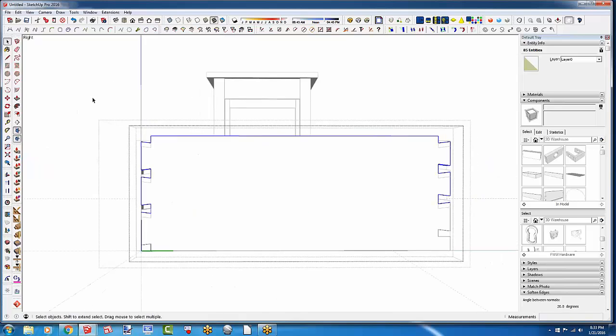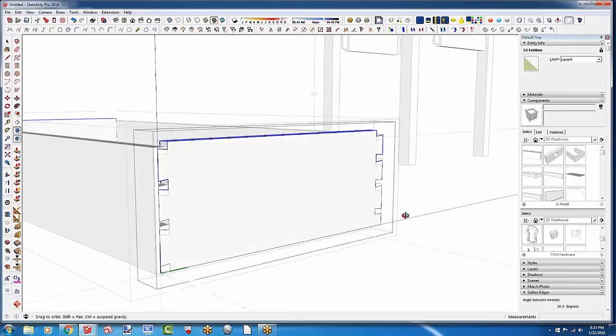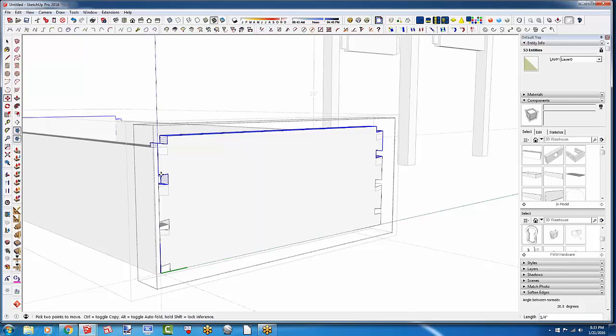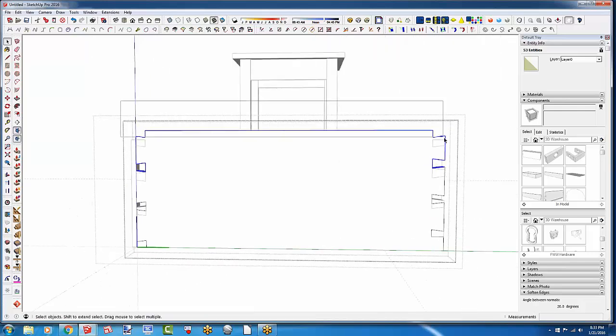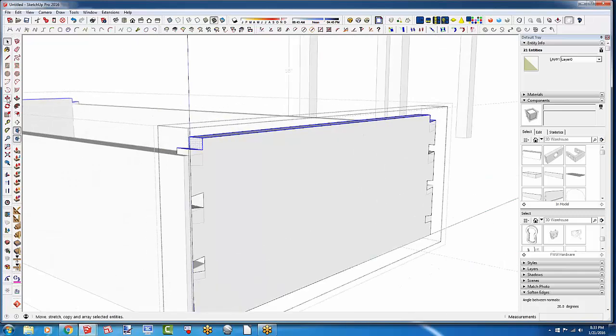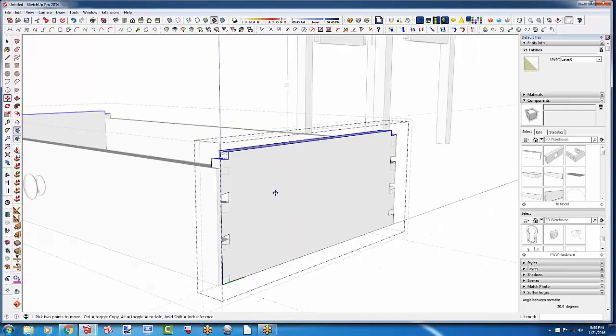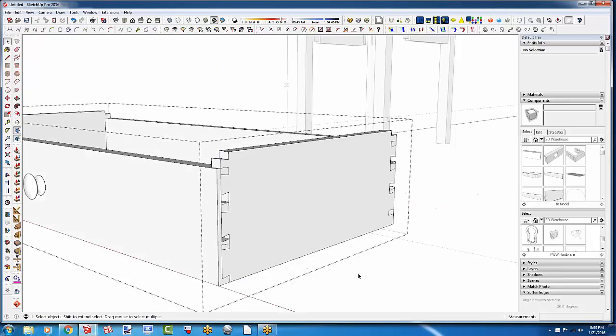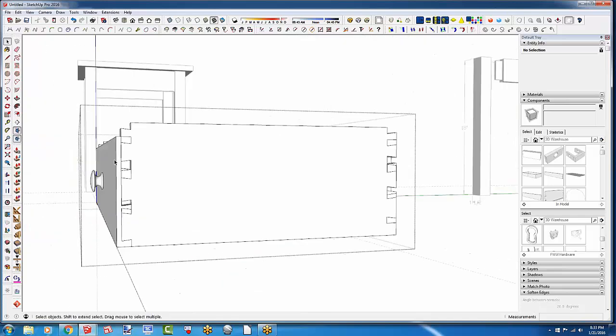So I'm just making left to right selections and move that 1/4 of an inch, and I just keep making selections of less and less stuff. And it doesn't matter where I grab here. Go up 3/4. So now I've just made the drawer sides 3/4 of an inch taller without modifying the width of the pins or the sockets.